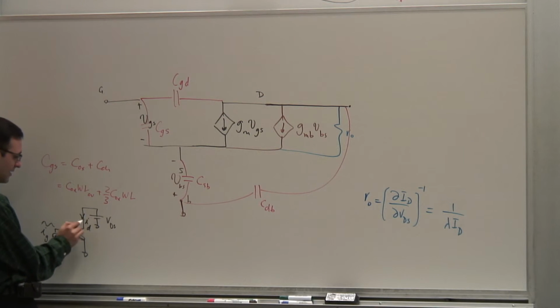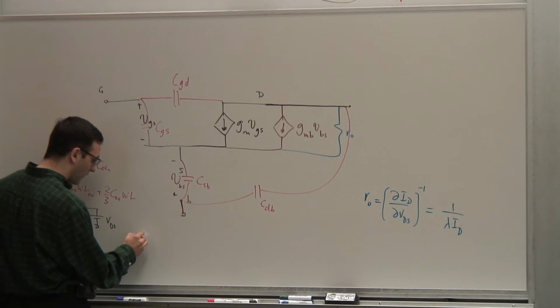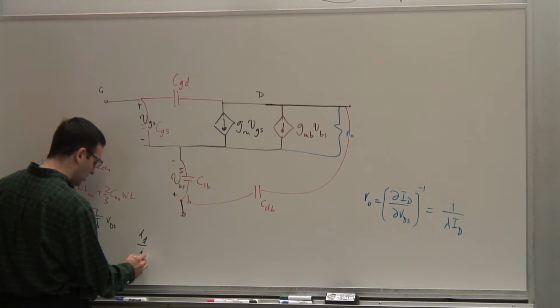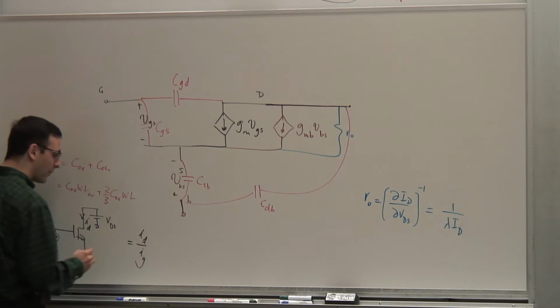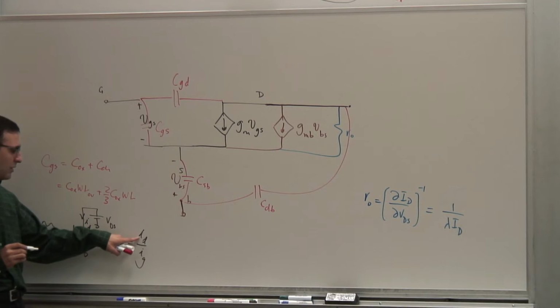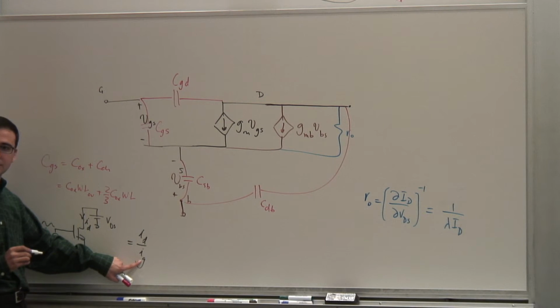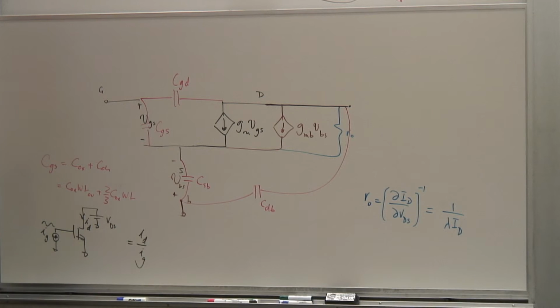But if you apply an AC current to this and change the frequency of the AC current, and you measure the AC current ID and calculate the ratio of ID over IG. So in the bipolar transistor, this was similar to IC over IB, right? We know what it was at low frequencies in a bipolar transistor. What was it? Beta. What is it at low frequencies in a MOSFET? Infinite, yeah, exactly. Because IG is 0 at low frequencies.